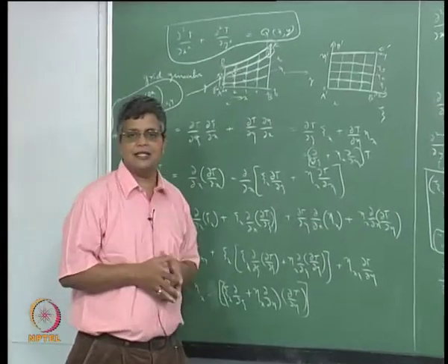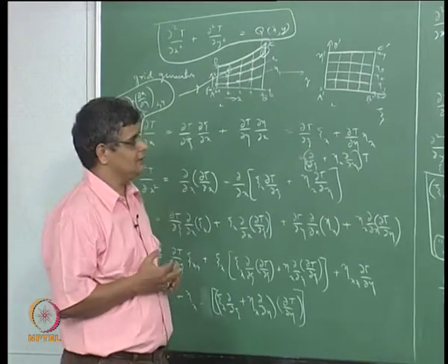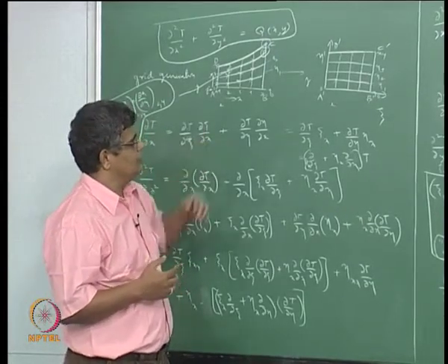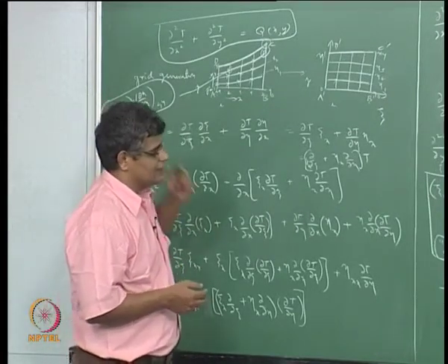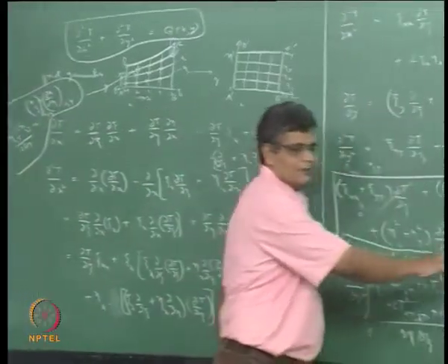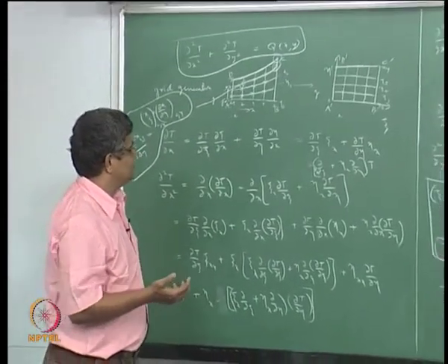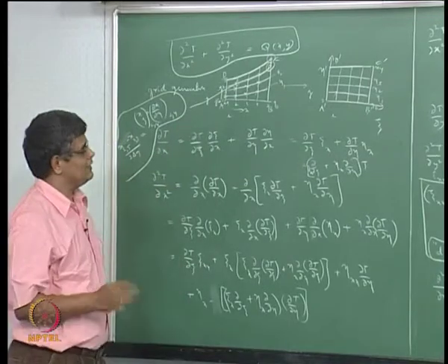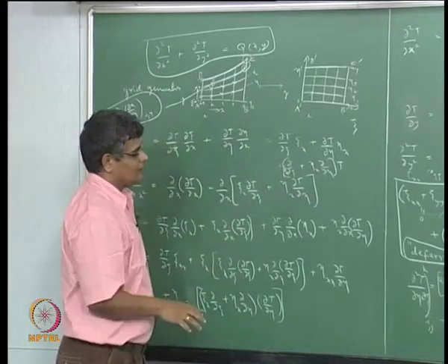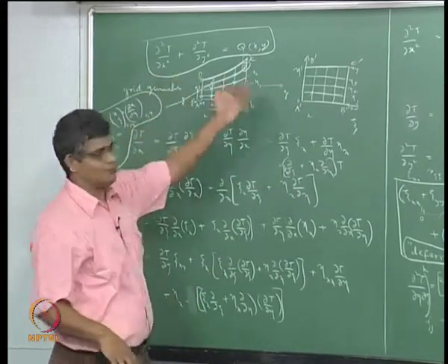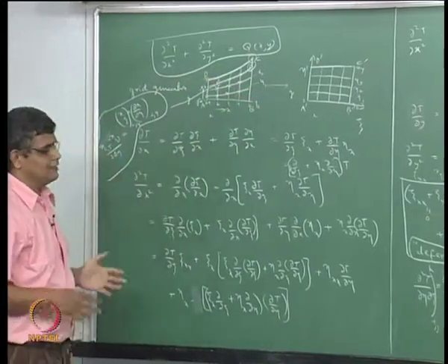But for a general three-dimensional case, it is not possible to ensure an orthogonal transformation, and so in such a case the cross derivative terms will appear and we have to deal with them. And grid generation transformation would be very easy if we had an analytical expression for the transformation, that is analytical expression for psi in terms of x, y, z or x in terms of psi, eta, zeta, like that. In the general case it is not possible.